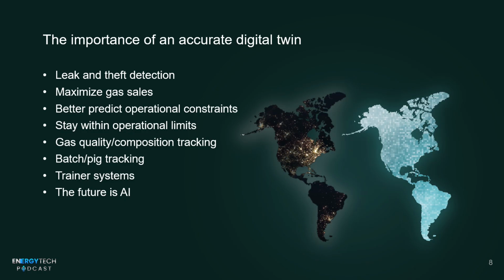So once you do have that digital twin, then you mentioned look-aheads. The next thing you can do, which is even more powerful, is you can take a snapshot of even a very complex gas network. Right. And that's coming from your live model. And it's telling you the composition, the flows, the pressures at every point in the network. And you can use that as a jumping off point to analyze some future scenario that you're interested in, such as how much gas could I deliver in Houston next Tuesday? Right. And that way you can unlock more value from your assets.